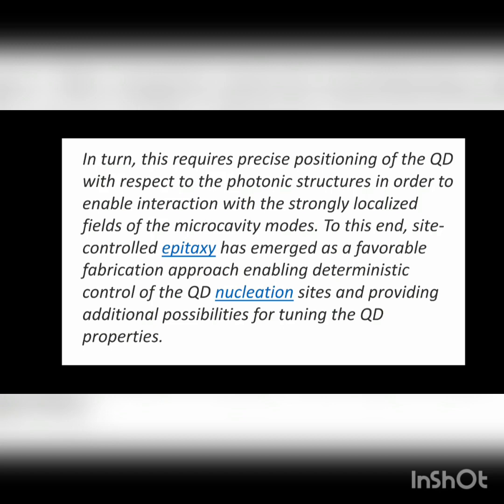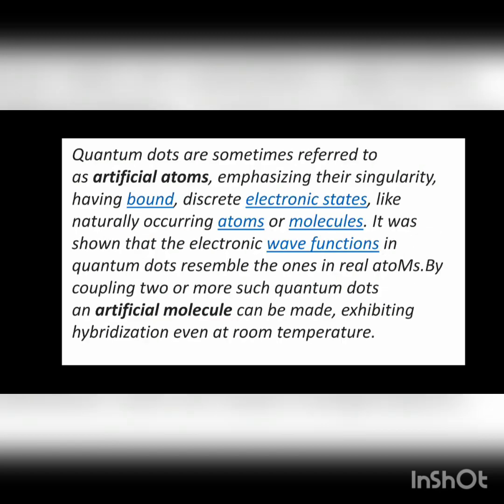To this end, site control epitaxy has emerged as a favorable fabrication approach, enabling deterministic control of the quantum dots' nucleation sites and providing additional possibilities of tuning the quantum dot properties.